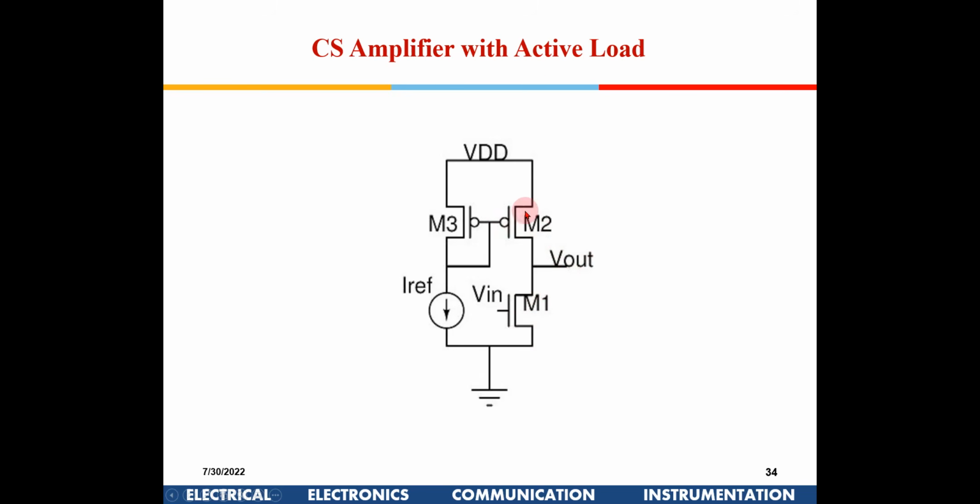If you keep exactly the same size of these transistors, and if you keep half the size of the width of this transistor, you will approximately get VDD by 2, because Pmos has got almost double the resistance if the same current is flowing here. If I keep the width of this M2 double that of M1, generally we will get VDD by 2 here.